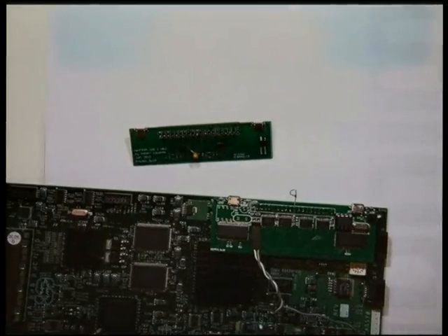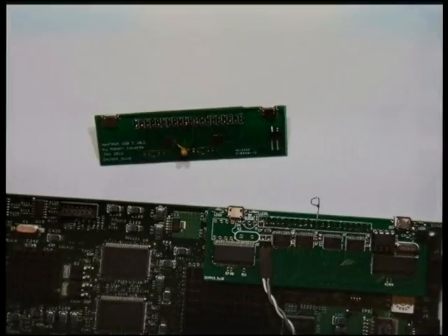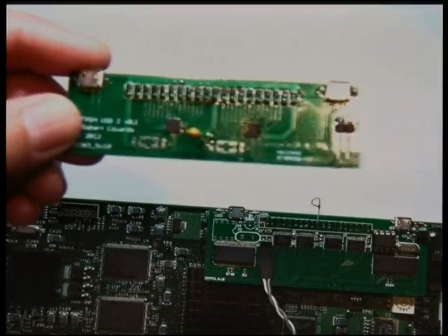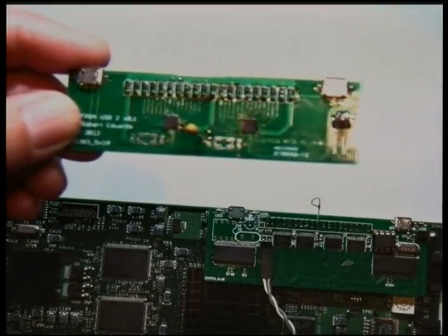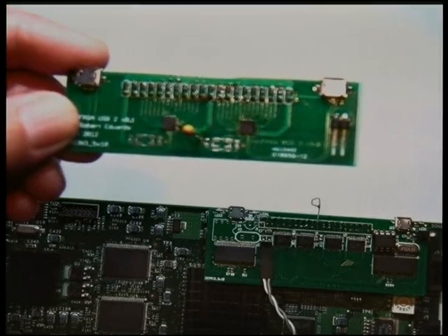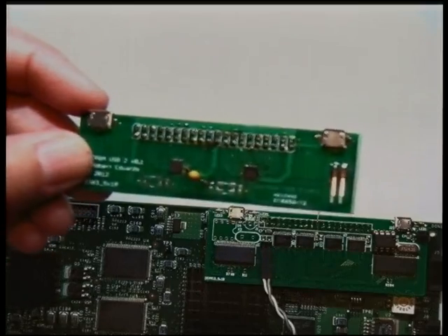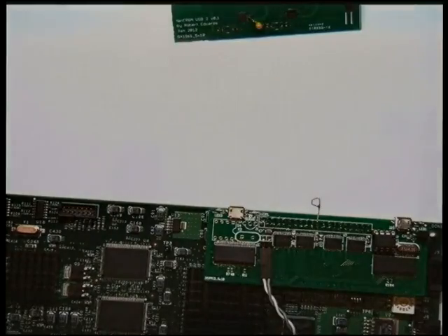So this is the version 0.1 board, and I'll zoom closer in on that. So anyway, it's got those 2 little tiny surface mount chips there, which we soldered with a hot air gun. All the pins are underneath them. There's no pins, there are just ball grid type things, and the debug connector and the 2 USB interfaces. And I think Bunny touched on the problems with this during his talk. It basically relies on implementing most of the USB protocol stack in FPGA code.